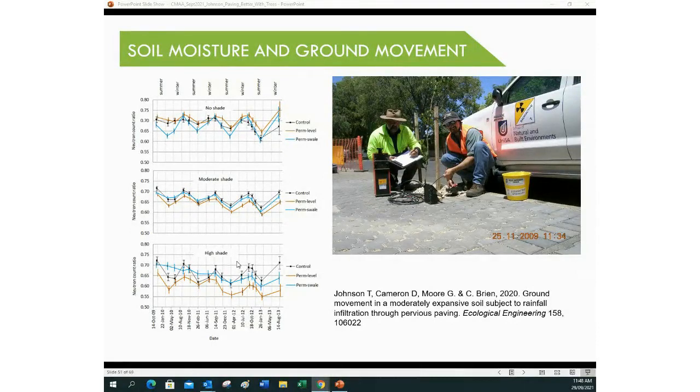Soil moisture down to 3 metres deep every half metre. And there was one occasion over 5 years of monitoring where the soil moisture was greater at half a metre deep below permeable paving than below impermeable. And that was immediately following the wettest start to the year on record. January and early March had really heavy rains. So our early March measurement showed wetter half a metre below the permeable paving. Every other measurement over nearly 5 years, it was drier below permeable pavement, even in the winter.